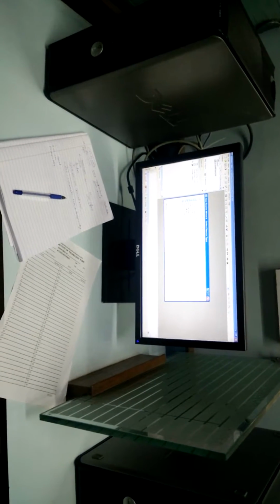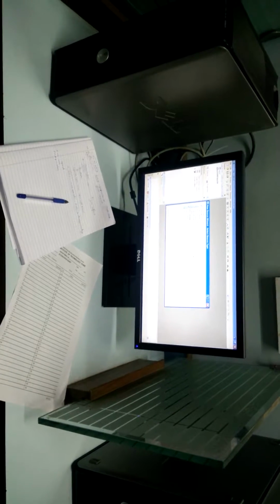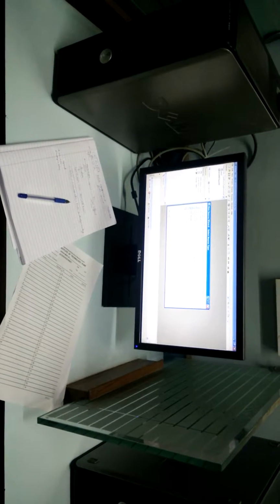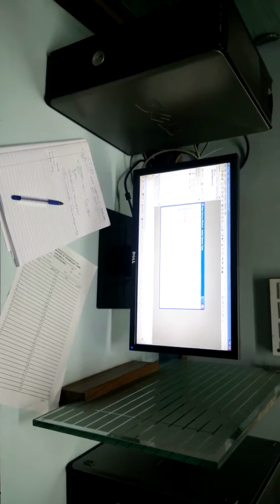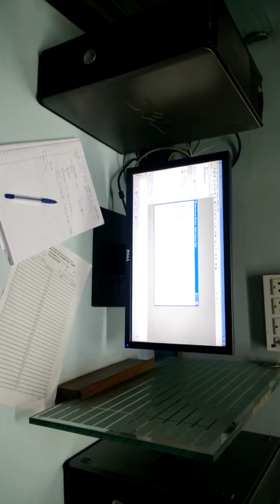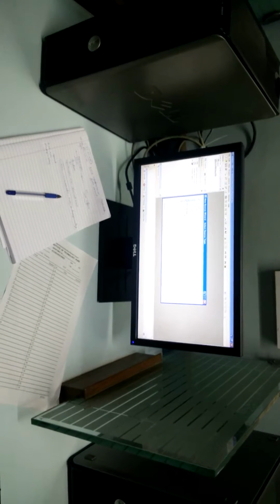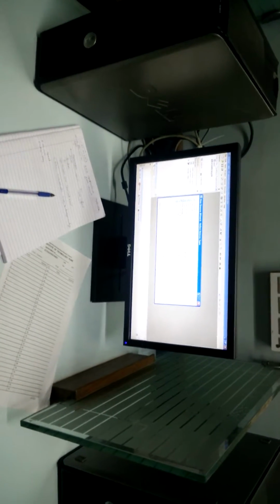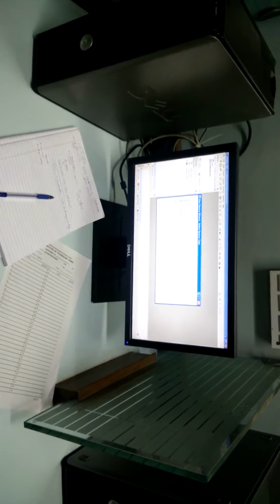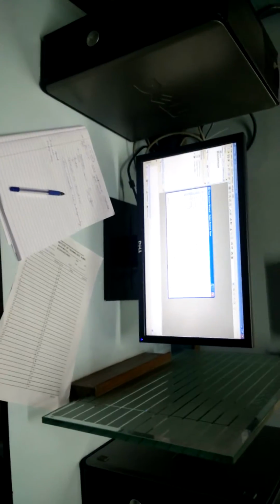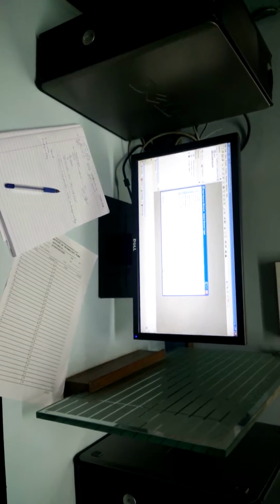Our first job is to write a VHDL module. So we will write a VHDL module and give it a name. The name of the VHDL module should be self-explanatory. Since we are designing a 2-input AND gate, I will give the name AND2. If you write AND, it cannot be used as the name of the project because it is a reserved word, a keyword. So you cannot give that name to the project or VHDL module. AND2 means I am designing a 2-input AND gate.